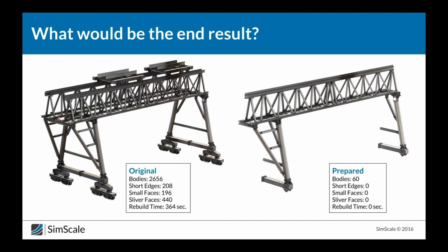Also here there's an obvious symmetry down the length of this crane, and so I was able to take advantage of that and only really model half of this geometry. But it should be noted that it's not just the geometry that needs to be symmetric, also the loads need to be symmetric.